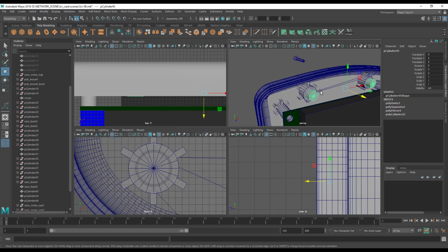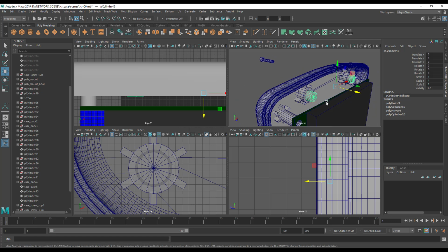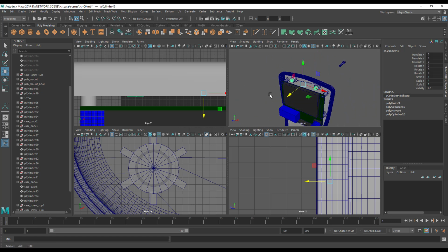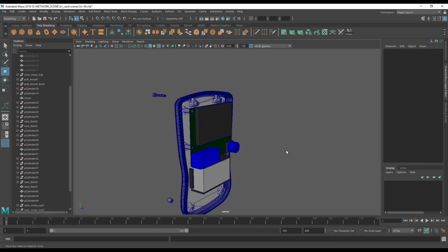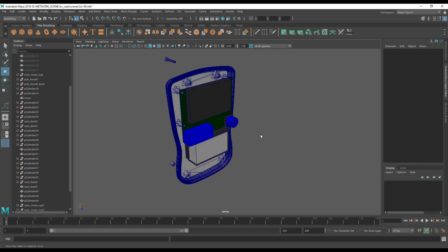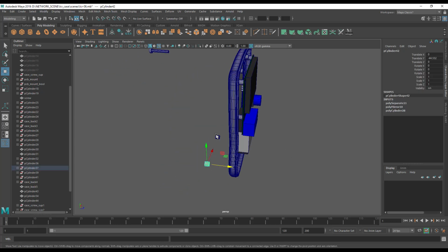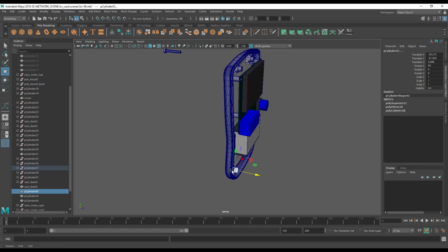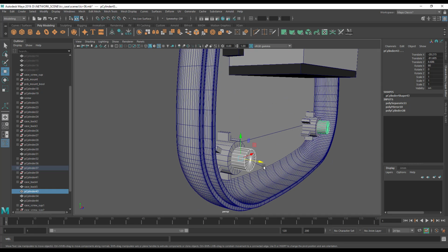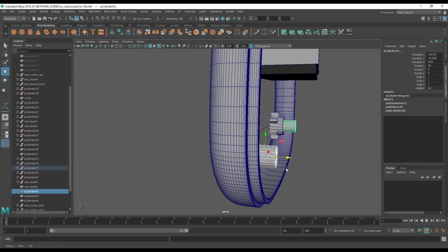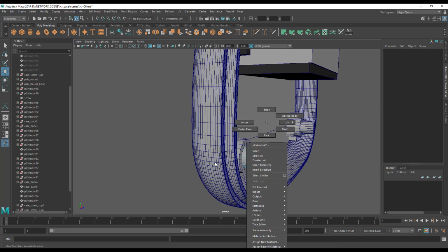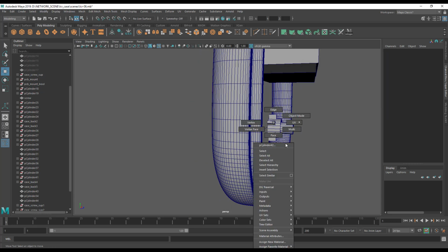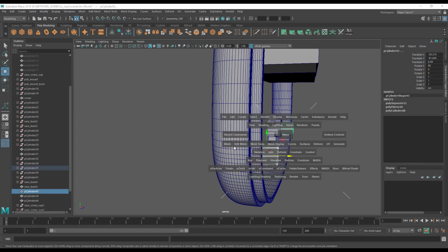So we need to put 1.4mm diameter holes in here, or 2.8mm circumference holes, and we need to do the same on the other side. So let's bring the front half, finally bring the front half of our case back, and we'll need to do the same thing with these ones down here. Now probably would have been better off doing this all at the same time, so my apologies there for the inefficiency, but it shouldn't actually take too long. You'll see if I do it without combining, I only get 1 set of verts at the same time, and that just leads to twice as much potential for error.